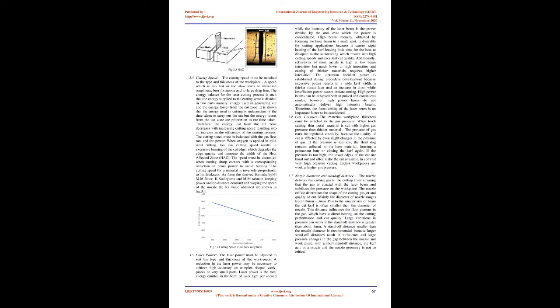Increasing gas pressure and cutting speed results in an increase of HAZ width. As the gas pressure increases, the power produced due to the exothermic reaction becomes higher and produces a higher HAZ width. The increase in laser power and standoff distance results in a decrease of HAZ width, but their effect seems to be negligible compared to the effect of cutting speed and gas pressure.